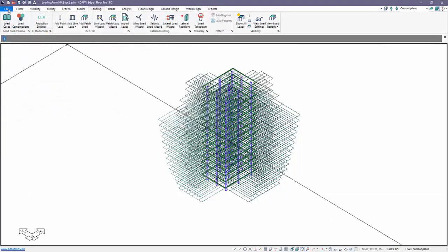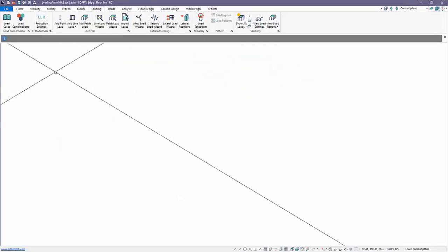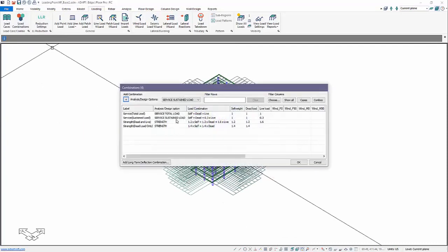And we're going to go ahead and import. You'll notice, by the way, that in this model under load combos, we have just the default combinations that are assigned to the selected design code under criteria. And these are gravity only combinations. Currently the program doesn't build out lateral combinations for wind and seismic. So the user is left to do this at least once, and then we can use this process to import the data.